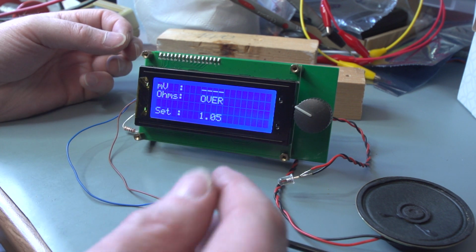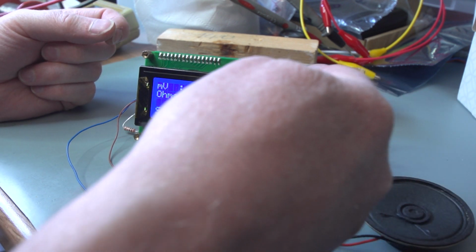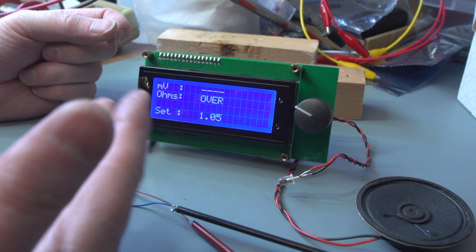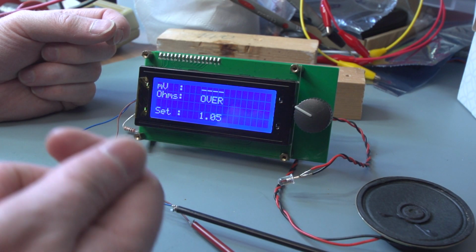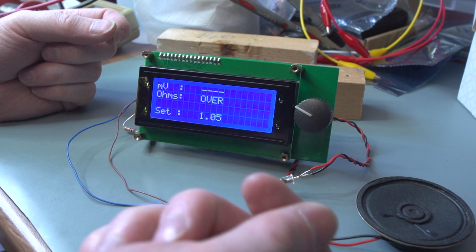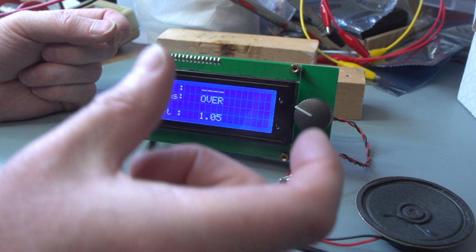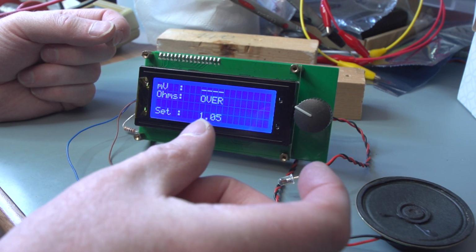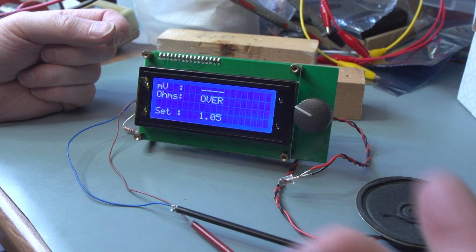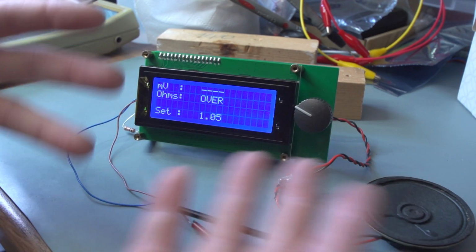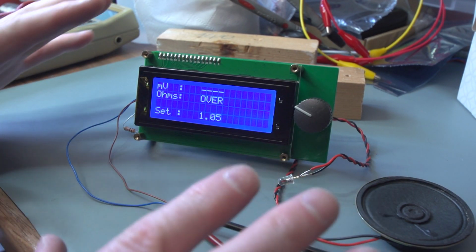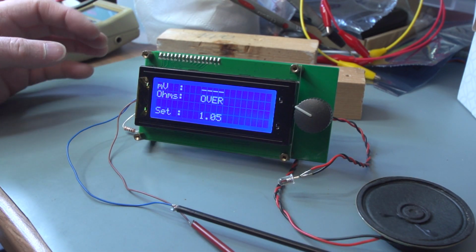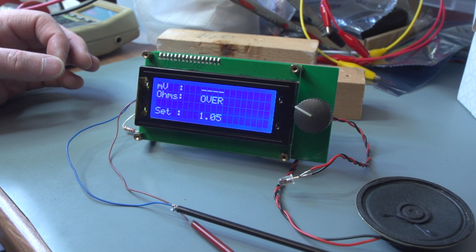Another option is to have a USB connection coming in. Use a USB socket. That automatically gives you 5 volts from a computer. If you plug it into a computer, or you plug it into a dedicated wall supply, like a little adapter, that will actually give you 5 volts through your USB lead, and that would power it up easily as well. So we've got loads of options. As long as we end up with 5 volts at around about 100 milliamps, we're good. So it's pretty easy to achieve.